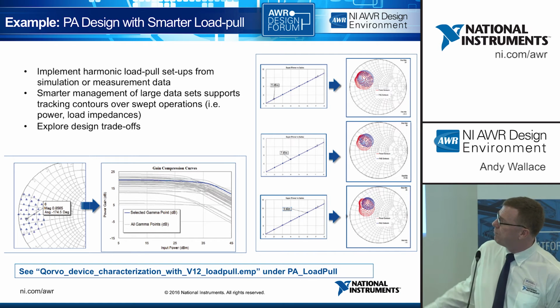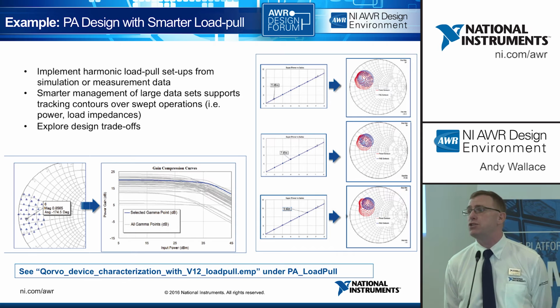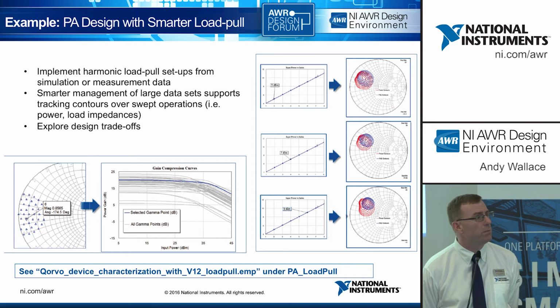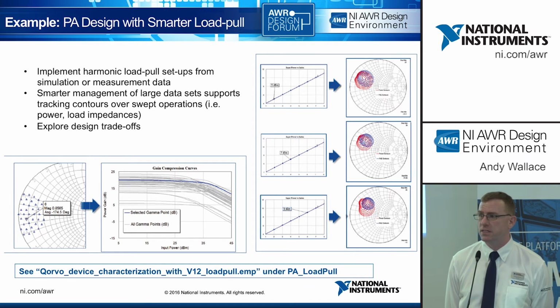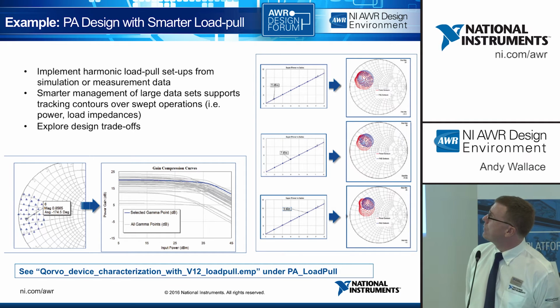It's not obvious from the graph, but some of these measurements are dynamic. So we have a marker here on this load pull point or source pull point, and the gain contour curve will become dynamic as you change that impedance point on the Smith chart. So as you left mouse click drag around the impedance point that you're offering or the load point that you're offering on a design, you actually see the active curves change and update. Very, very useful.